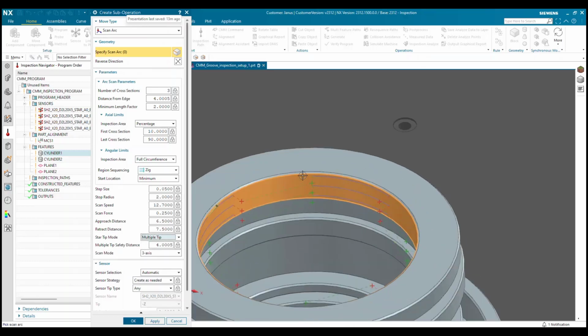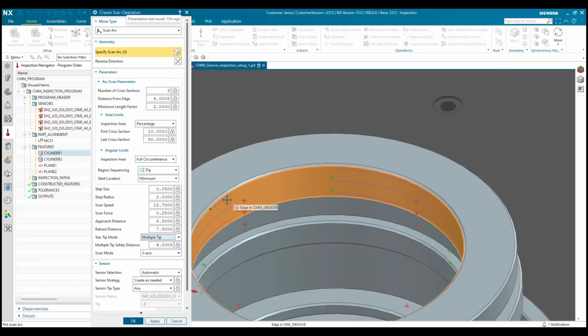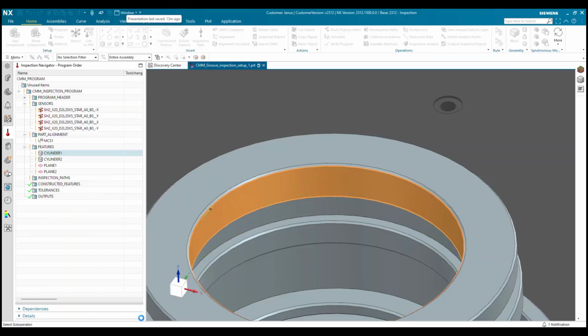The multi-tip generates the inspection pass section by section where the probe can achieve the highest possible scan angle with the given conditions, which means that we can, for example, reduce the safety distance and then the transition moves get shorter and larger section of the part can be inspected.